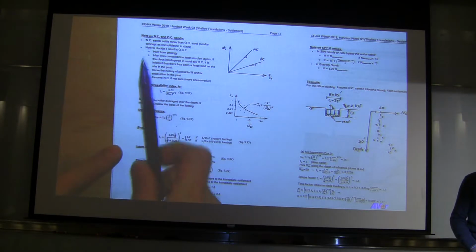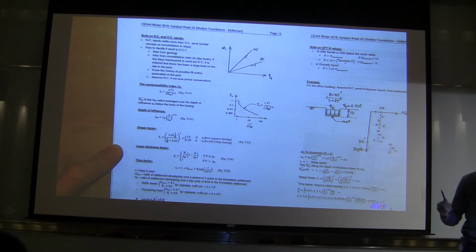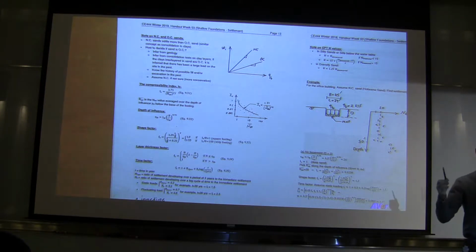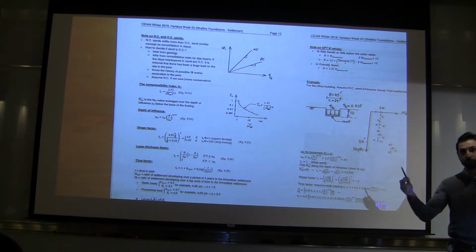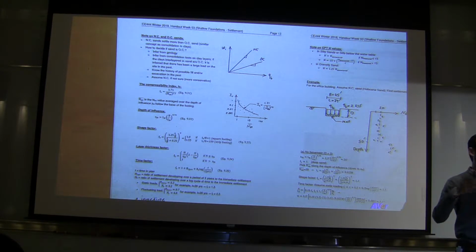One way is to infer from geology. So the geologists might come and say, well, this area was under glaciers, so it was loaded before, and now that the glaciers are gone, everything underneath here, whether it's sand or clay, is OC.